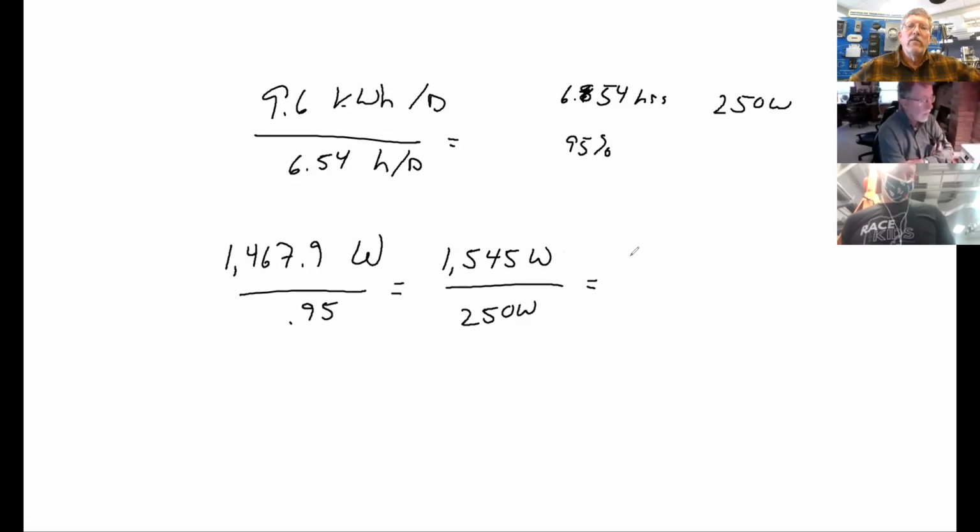So at this point, we're going to need 6.18 or something like that. So you need 7. Yeah, 6.18, so we'd round up to 7 panels. So that's how you would figure that one.